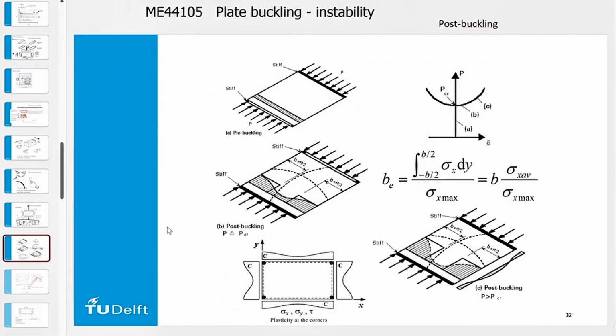Then something else, and as I told you with beam buckling, if a beam buckles, then there is no reserve capacity, and if you go above the yielding at a certain location, then your full structure collapses. But for plate buckling, that is different, especially if the buckling limit for a plate is lower than the yield limit. Suppose I have a very wide plate, so that the B divided by T is bigger than this 56. Then what happens if I apply a load on one edge?